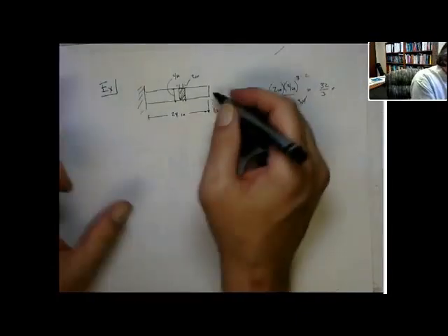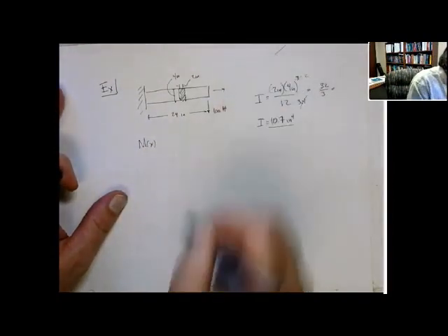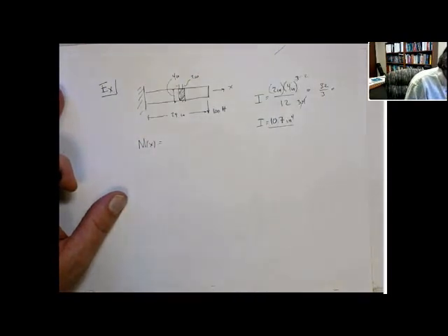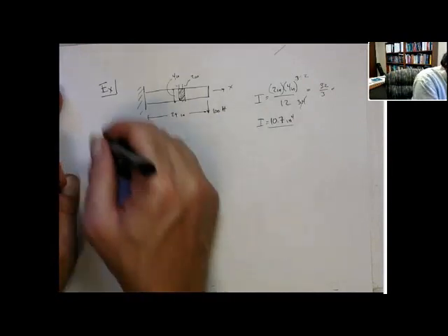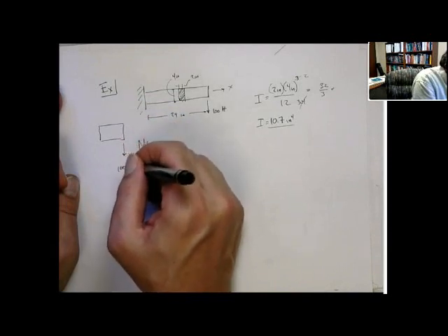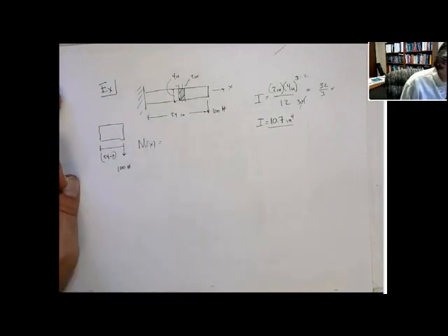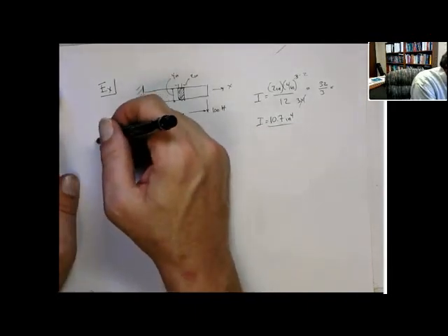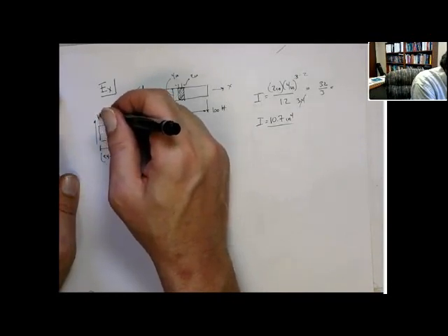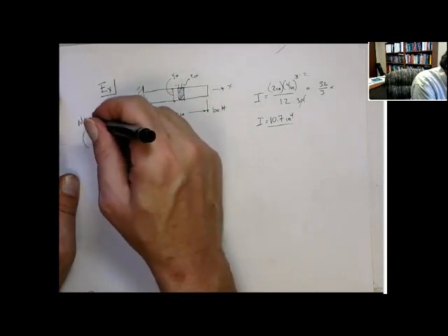What about the bending moment? Well, we can look at this, and we've done this problem before. We know that the bending moment function of x, the max is going to be here. The bending moment in this case is 100 pounds, and this distance here is 24 minus x. Shear this way is actually positive shear, constant. Bending moment is positive in this direction.